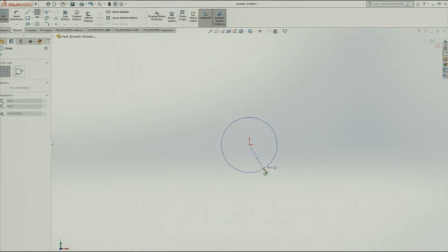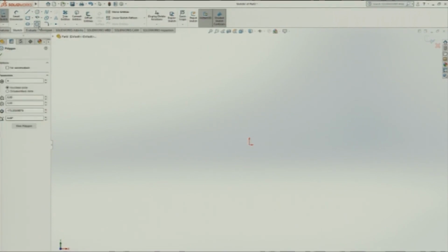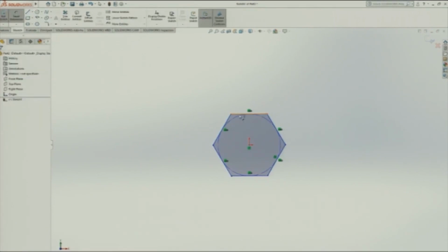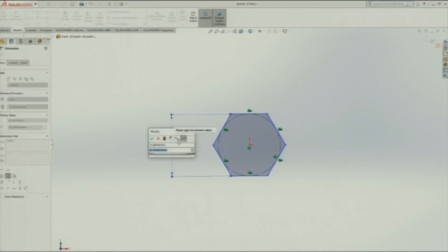Okay, for bolt I think let me start from the head only. The head for the bolt is hexagonal, I am selecting hexagonal bolt. So, a hexagon here. A random size is selected, let me put the dimensions here. This is width across the edges, which is actually 1.5 d plus 3 mm.